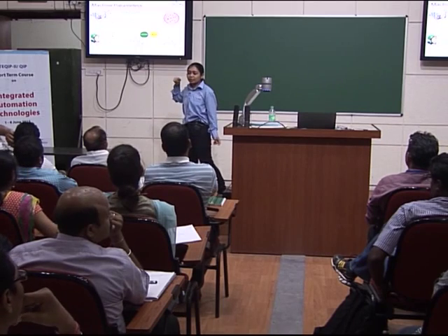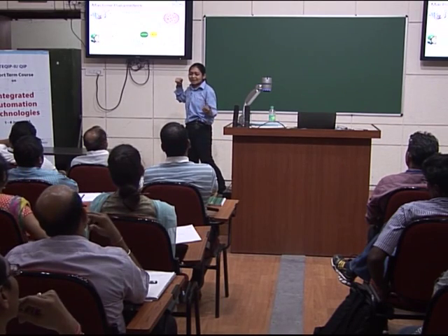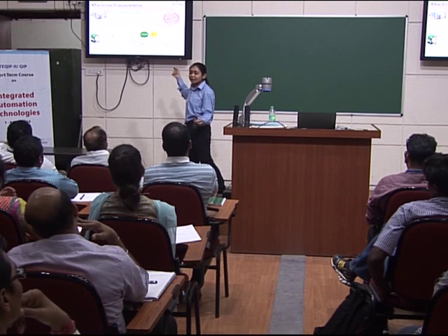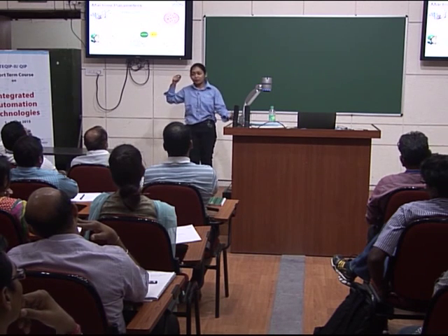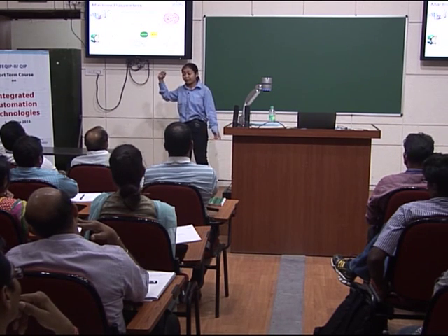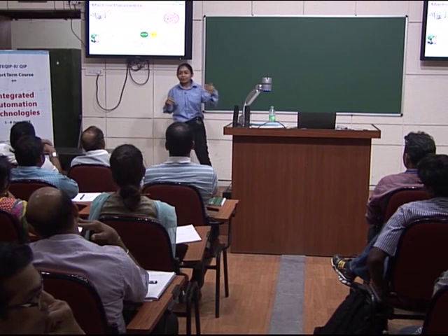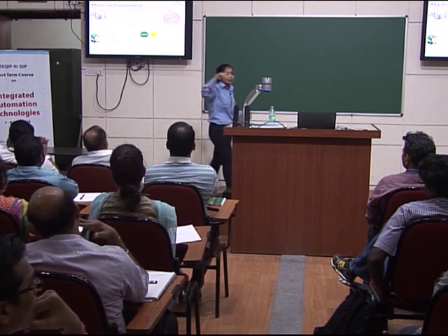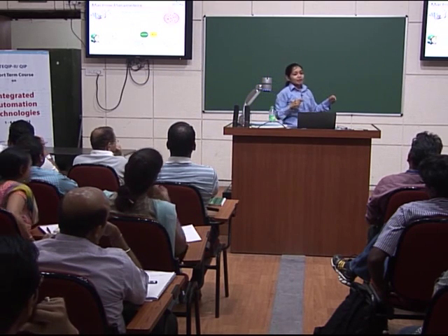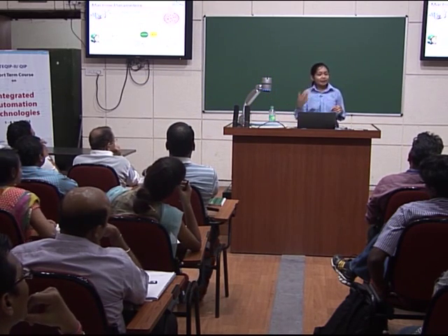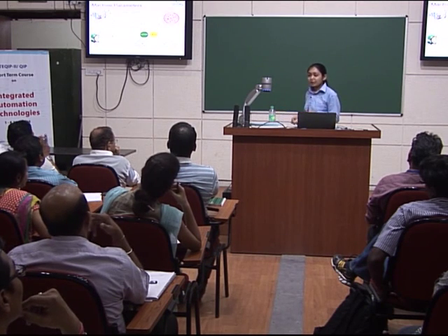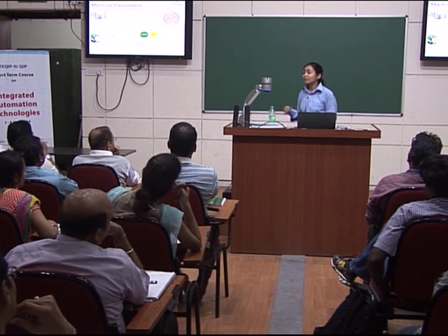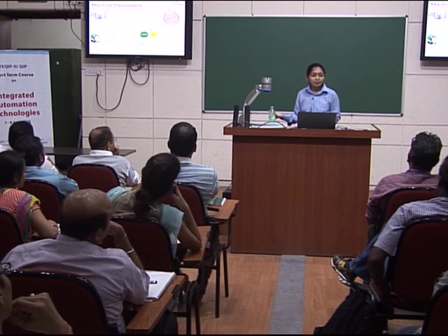Generally OEE is measured for a set time. You can say I want OEE measured for 1 day, or I want OEE measured for 1 month. So you can set the basis. And generally we display the OEE on the HMI itself, so that you know what is the OEE that the machine is giving, and then you can reset your OEE so that it starts calculating again. From the start till the period, you should be able to know what has been the effectiveness of the machine.